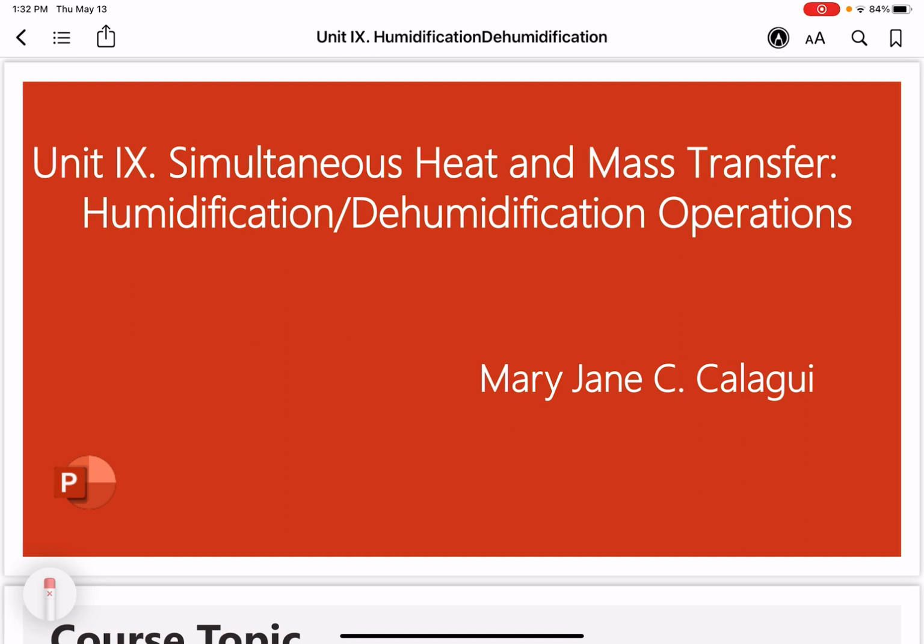One of the most important psychrometric operations is the air-water contact operation. These operations are also referred to as the humidification process. In day-to-day practice, whenever reference is made to psychrometric operations, it is always understood to be a humidification process, unless clarified. If it is the other way around, it is the dehumidification operation.